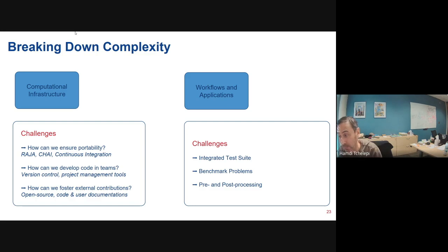But you could definitely add on top of that dynamic adaptive mesh refinement to, say, resolve the transport dynamics more accurately near wells than elsewhere. And actually, we are embarking on things like adaptive implicit methods and mixing implicit and explicit treatment of the transport, and maybe ultimately go for dynamic mesh refinement.